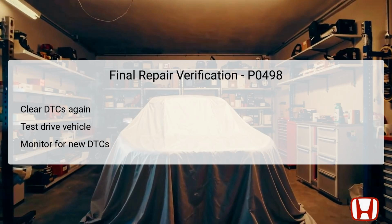Monitor the vehicle's performance during this test drive, while paying particular attention to the dashboard displays for any illumination of warning lights. Ensure that no new DTCs appear during this monitoring phase, as this indicates that the repairs were successful and the EVAP system functions as intended. Confirming the absence of DTCs revalidates that the issue has been effectively addressed.